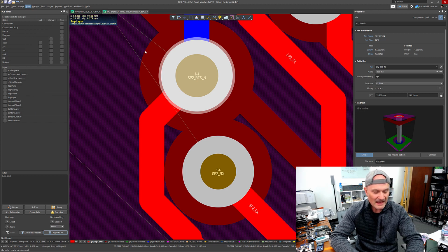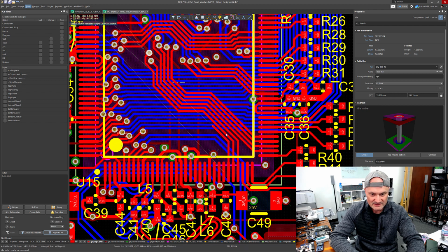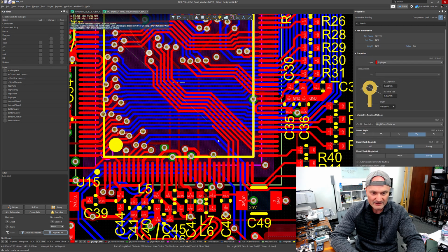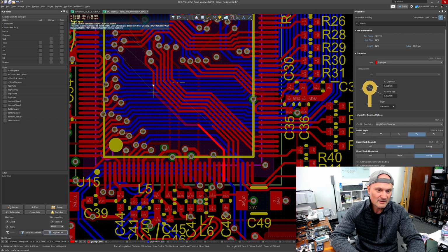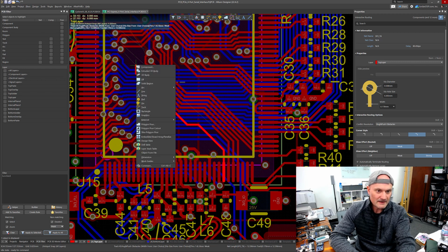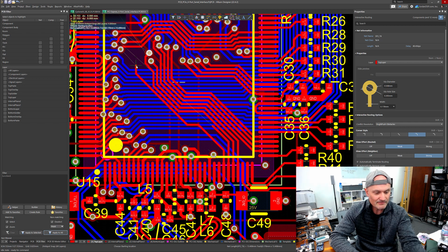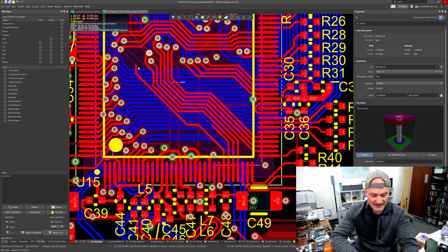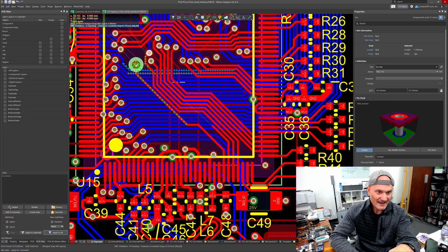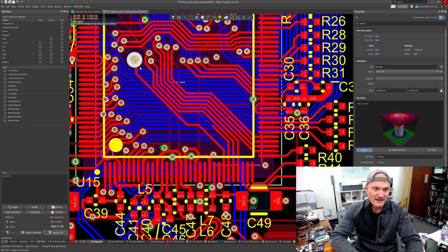That's the absolute beginner's way of doing it. Let's do that real quick. So I'm routing a board, need to change layers. Want to go up here. So then I do now PV shortcut, but that's not working because I haven't exited the routing command yet. So I have to actually stop, hit escape, right? Then do PV. And now it's giving me this gigantic, unearthly, stupid via.